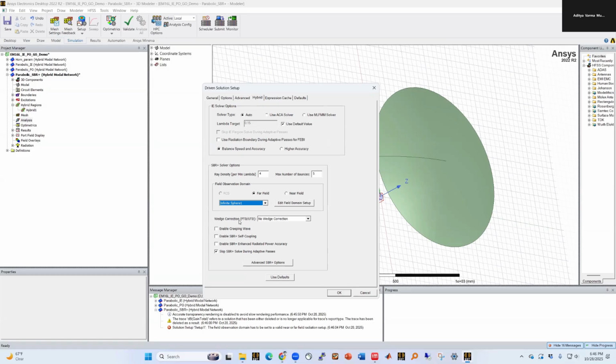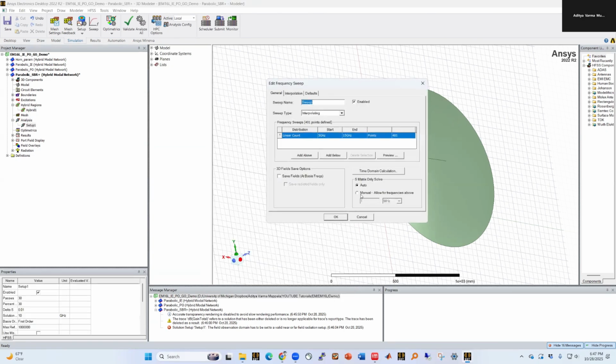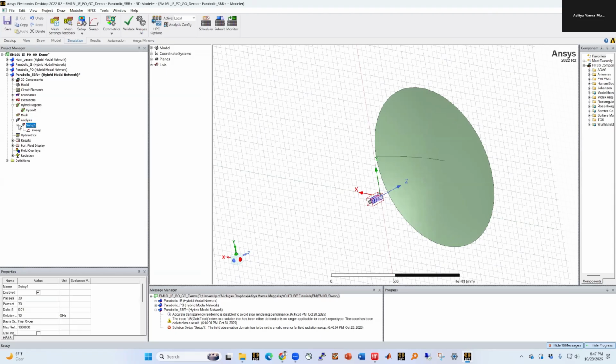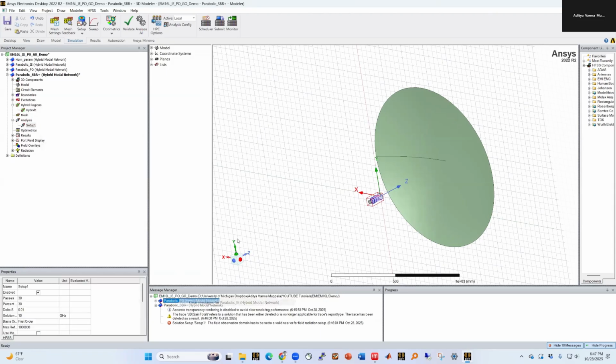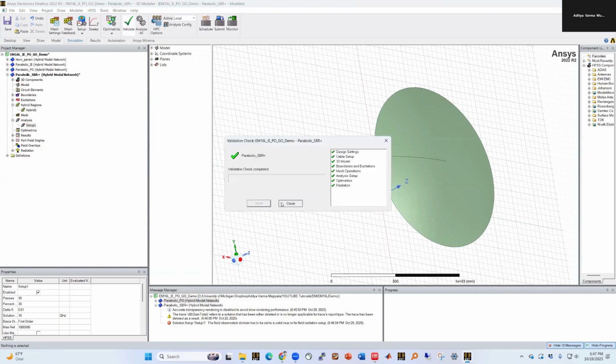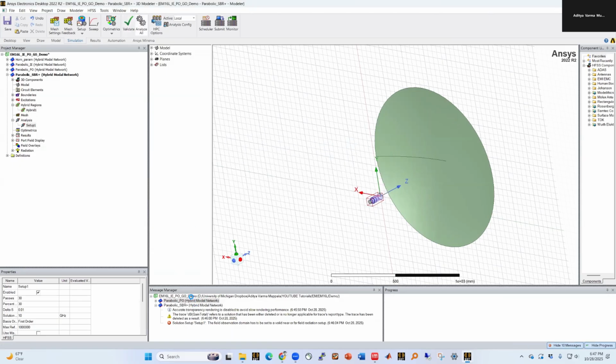And you can add extra wedge correction factors. We really just discussed at a very high level what PTD is. Creeping wave we haven't really discussed yet, but you can add these correction factors if you like. And now we'll just leave them. Okay, and then we can delete this. And now we can run the simulation and see what happens, and compare them with the other two cases.